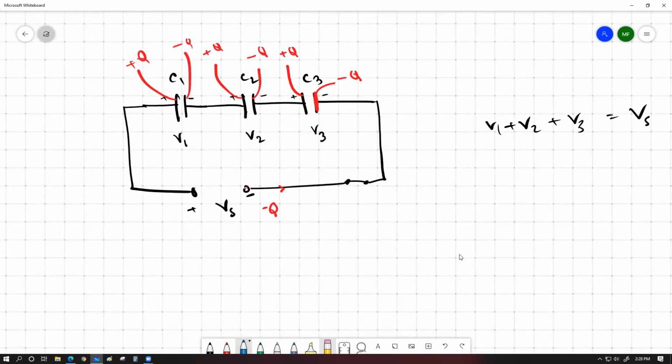So have a look, if you consider this much segment of a circuit, the right plate of the first capacitor and the left plate of the second capacitor. These two plates are practically not physically electrically connected to the other part of the circuit, which means electrons cannot leave altogether from here. All that they can do is accumulate in one place by producing a shortage in the other place. So whenever we connected the source with this capacitor combination, the very right plate became negatively charged and the very left plate became positively charged because of the source. Within these in-between segments, the charges moved apart by exactly equal amount so that they could produce equal and opposite charge on both sides. Have a look.